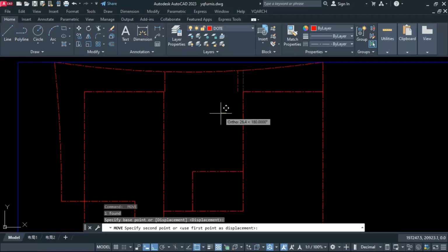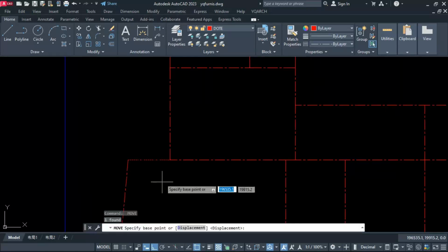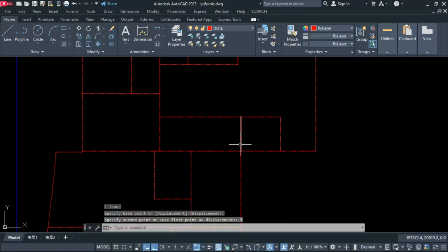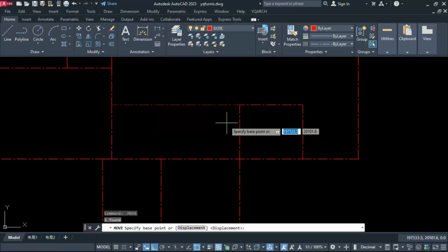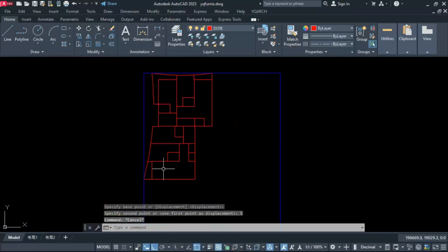So to make auto wall, wherever 20 centimeter, you have to leave corner space, as I am leaving, if you see here, because this will connect your 20 centimeter to 10 centimeter straight line. So you must leave 5 cm space. Okay.